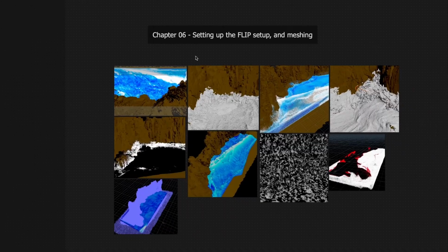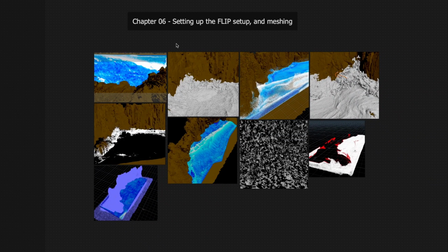And then we'll jump into chapter 6, where we'll be setting the flip settings for this shot. So in here we'll dive in and use some of what we learned in the previous test bench and previous episodes to customize our flip settings, to create some custom collision forces and collision behavior around the cliffs, and generally direct our simulation as we want it to be.